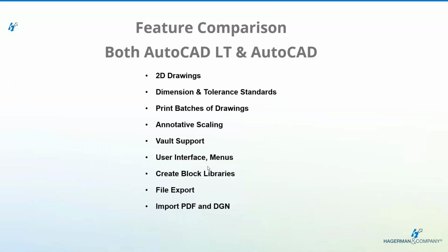They were all nice, but annotative scaling is a game changer. If you are not familiar with it, go watch some videos and get some training on it, because it will change the way you work in AutoCAD. That's true for both AutoCAD LT and AutoCAD.